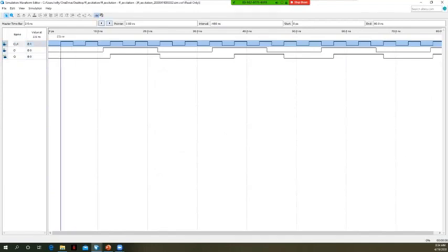So here we can see at 2.5 nanoseconds, we have a rising clock edge. By that rising edge, we mean that the signal level is transitioning from a 0 to a 1. So it's rising from 0 to 1. And this flip-flop is positive clock edge triggered or rising clock edge triggered. They both mean the same thing. At this time, D is a 0. So that means Q will be a 0. And Q will hold its value until the next rising clock edge.